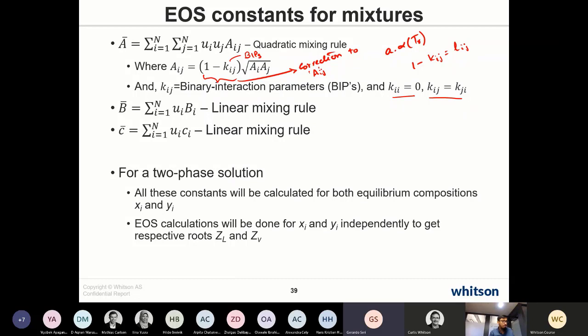Yeah, Bilal, it's normal. I've seen it in several reports where they say the binary coefficients between the lights and heavies are not matched, in order to avoid losing precision on extrapolations outside the conditions where we've done the equation of state. How does that relate?